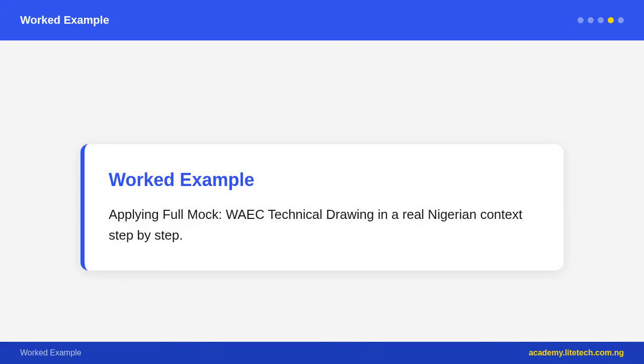Bearings support rotating shafts and reduce friction. 2 main categories. Sliding, plain, bearings: the shaft slides on a lubricated bearing surface. Simple, cheap, compact. Bush bearings, journal bearings. Rolling element bearings: balls or rollers between inner race on the shaft and outer race in the housing. Rolling friction is much less than sliding friction.